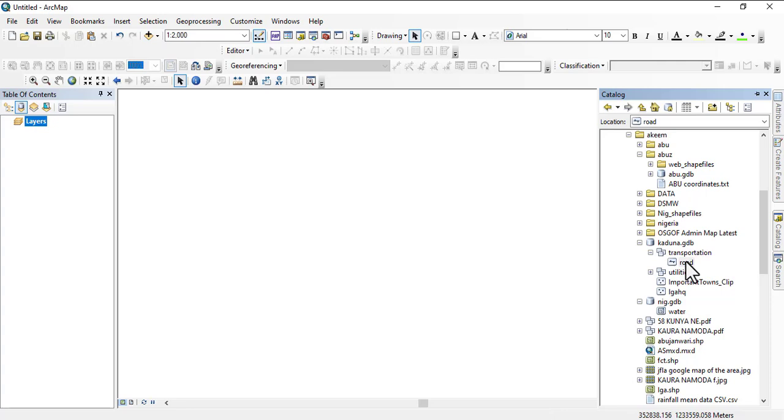To illustrate the range domain, we talked about it having a minimal and a maximal value. So we're going to illustrate it so that we see how it works. Take for example, we want to fill in the length of each road we have within the study area. We're looking at how long the road is, and we don't want to use the general shape length. We want to have our own. This road we need to be between maybe 2 meters and 2000 meters, that's 2 kilometers. So that's what we're going to be doing today.